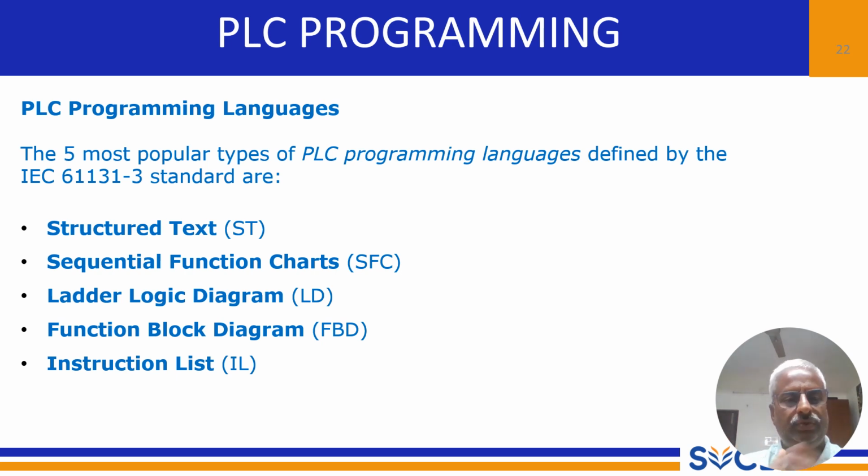So as per IEC 61131, we have the structured text programming method, simply called ST, sequential function charts, SFC, ladder logic program, LD, function block diagram, FBD, and instruction list.